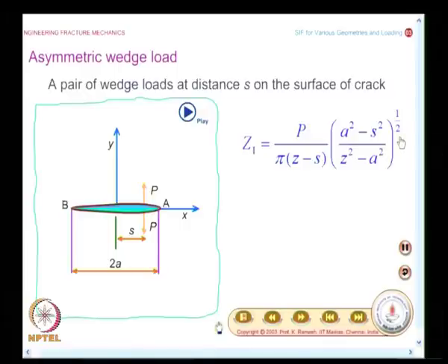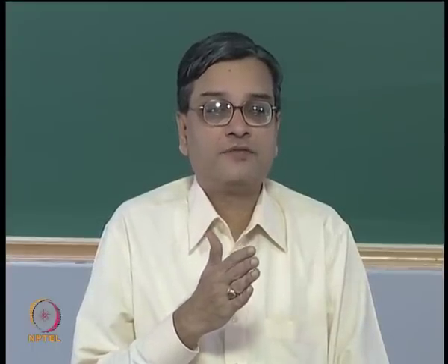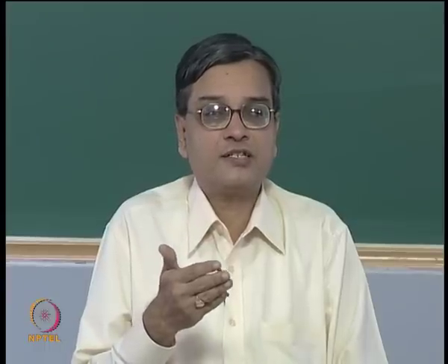Once the stress function is given, it is now child's play for you. Shift the origin to the crack tip and then apply the definition of SIF.